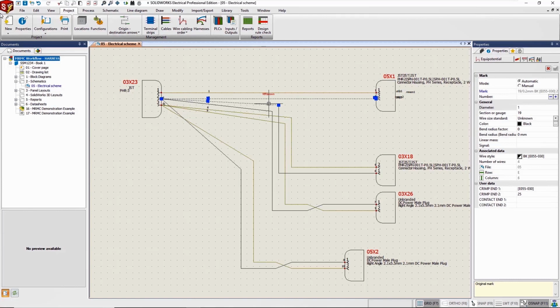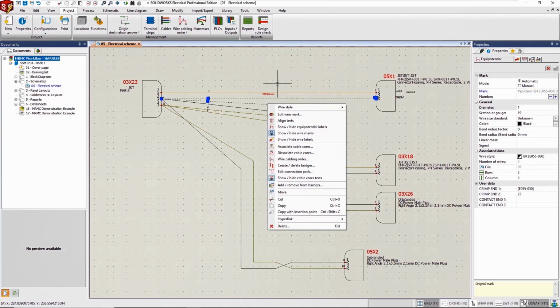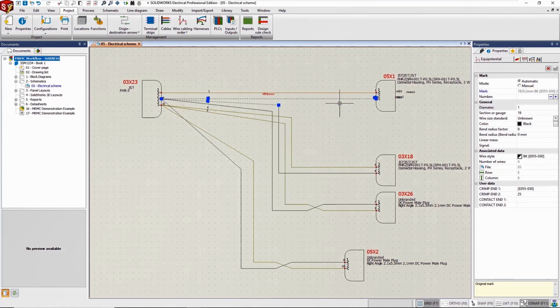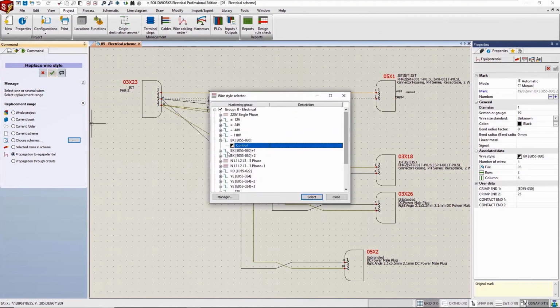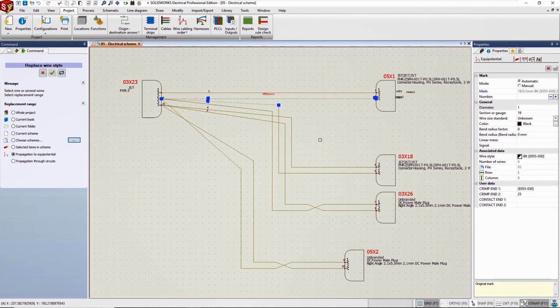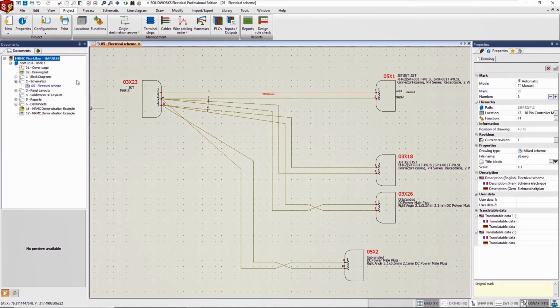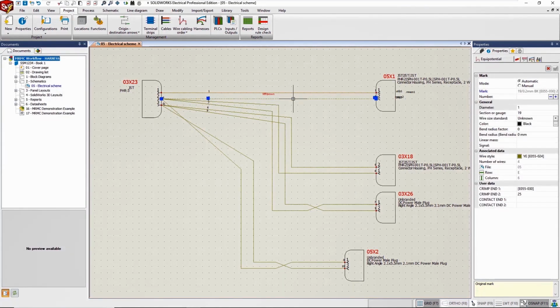In 2019 and previous releases, it was necessary to delete the route and recreate it if any changes to the schematic had taken place. In this example though, we're going to change the wire style, we can change the thickness of the wire as well. We could even go to the extent of changing a connector, maybe adding or removing a connector from the completed loom. Now in 2020 the data is re-imported, maintaining any route changes that had taken place.